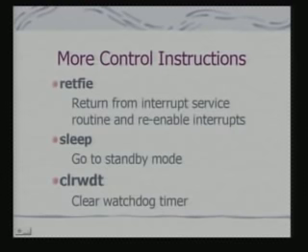What does that mean? It means that when an interrupt occurs and you are servicing the interrupt, interrupts can be disabled, so that the current interrupt service routine is not further interrupted. Now, this is also important for PIC. Why? Because the interrupt service routines need to be managed.